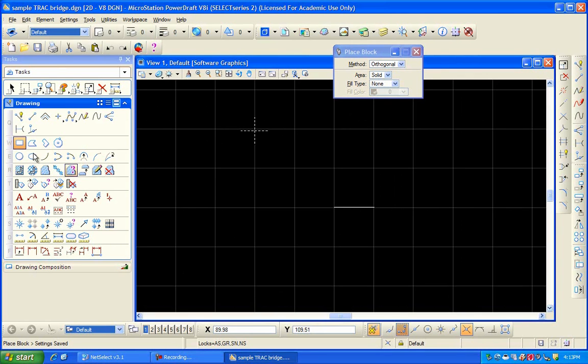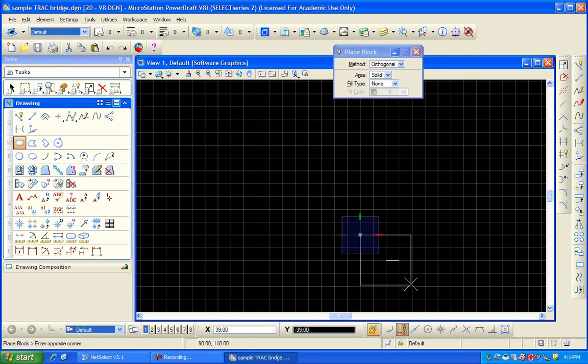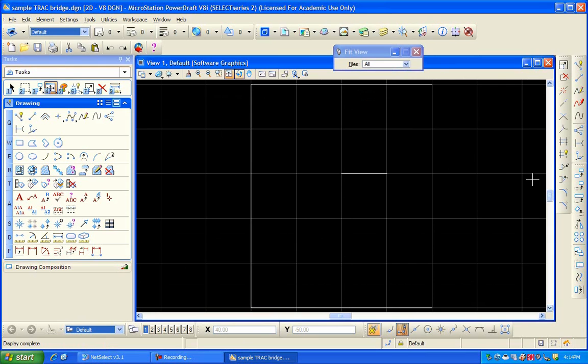So to do my border, I'm going to do my block again, and I'm just going to hold right the intersection there, tentative snap with my middle button, and then I'm going to drag my rectangle 1, 2, 3, 4 wide by 1, 2, 3, 4, 5. So if I snap there, oh, I can tell I snapped one too low. Now if I do a fit view, I should be zoomed into an area that's 40 inches wide by 50 inches tall.